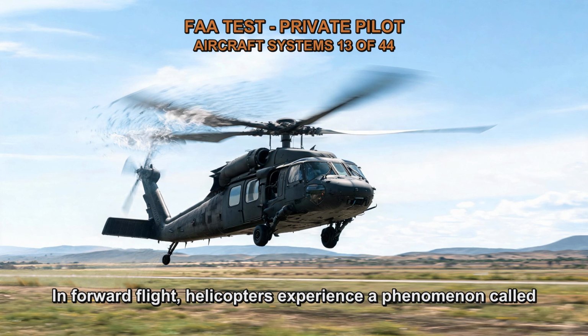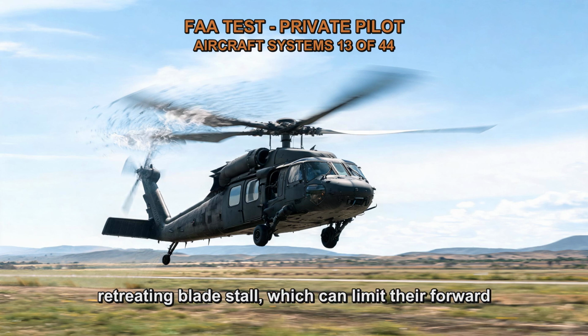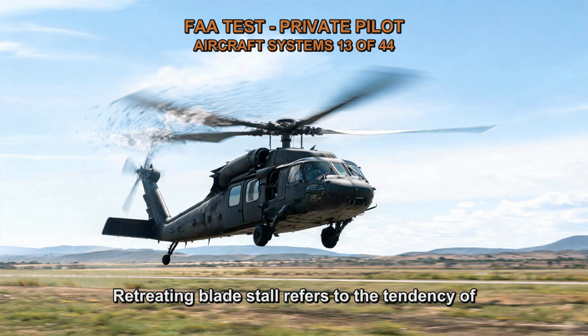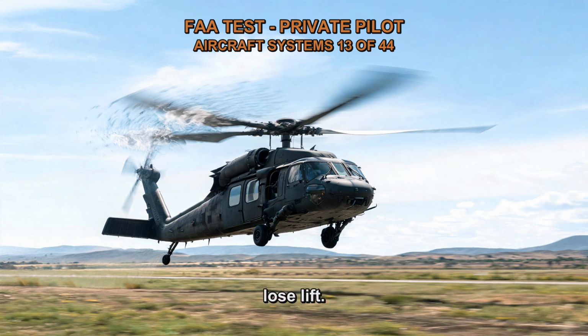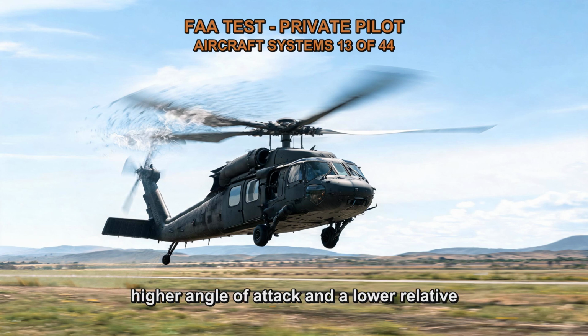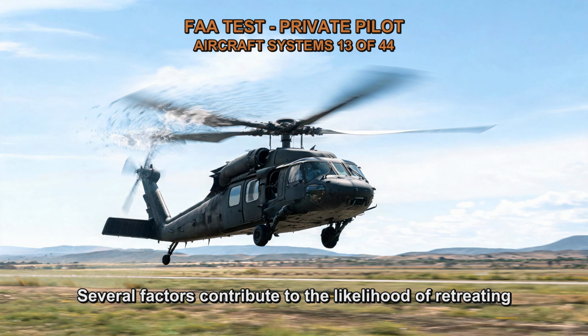In forward flight, helicopters experience a phenomenon called retreating blade stall, which can limit their forward airspeed. Retreating blade stall refers to the tendency of the blade on the side opposite to the direction of flight, the retreating side, to stall or lose lift. This occurs because the retreating blade experiences a higher angle of attack and a lower relative wind speed compared to the advancing blade. Several factors contribute to the likelihood of retreating blade stall occurring during high-speed operations.